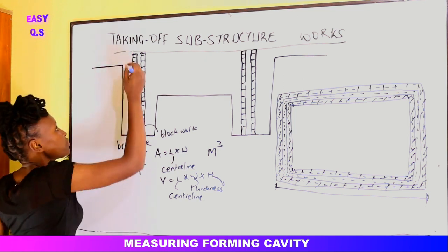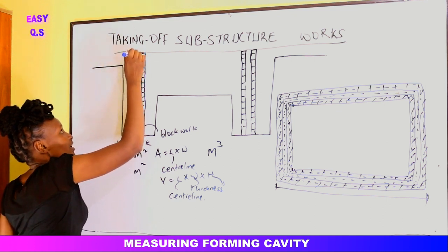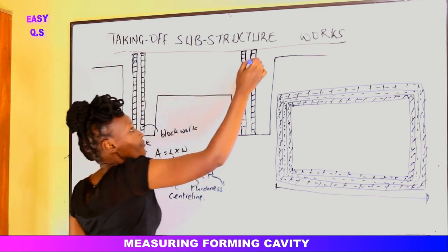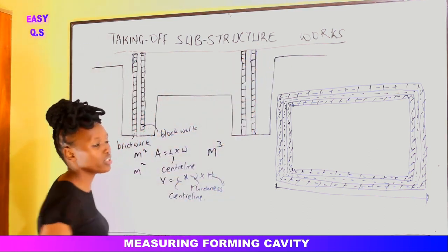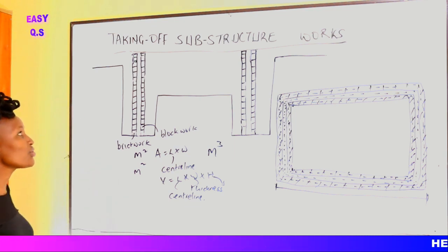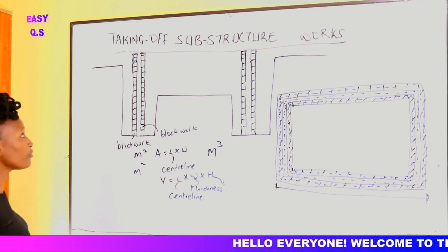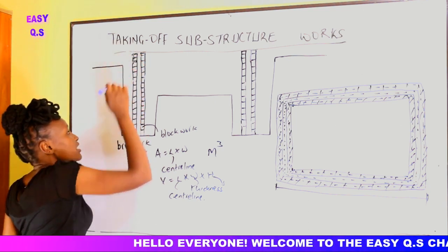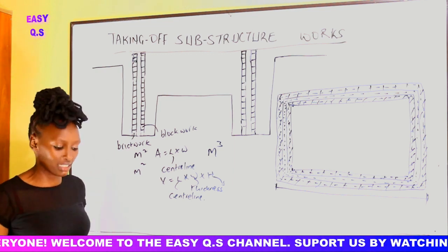But these bricks which are here, you see this, if this is the ground level, these bricks that are here and here, they are on top of the ground, so they are facing bricks. We need to do some adjustment, some change to the brickwork that we had taken off. So these two courses, we need to adjust them, and they should be on the superstructure side.